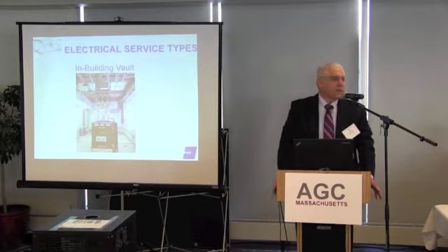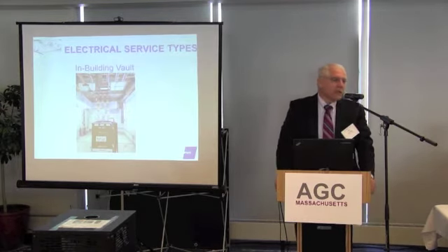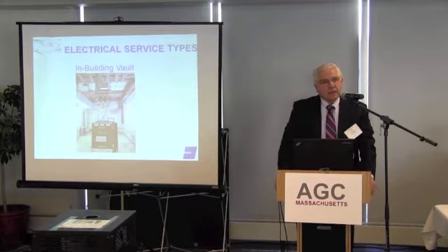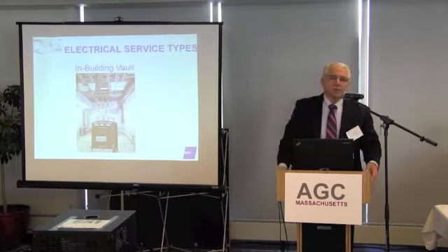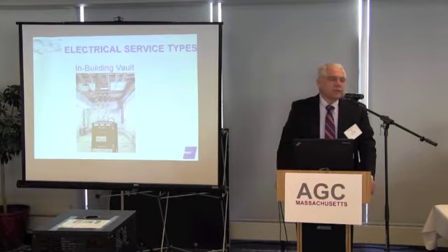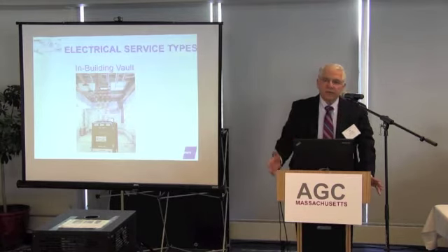So you have an underground inspector that'll look at the conduit. If you're taking the feed from overhead, you have an overhead line supervisor that has to approve any work that's being done. And when you get into the vault, you have an inspector that will look at the vault structure. Then, when the vault is prepared inside the building, there's a grounding network.